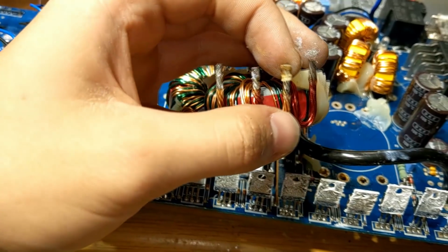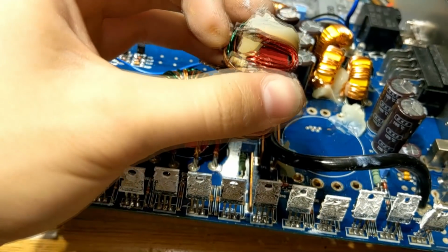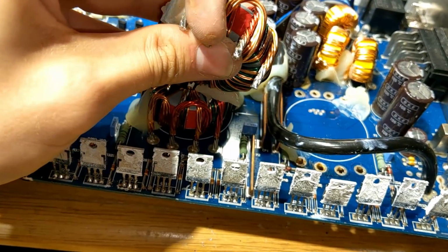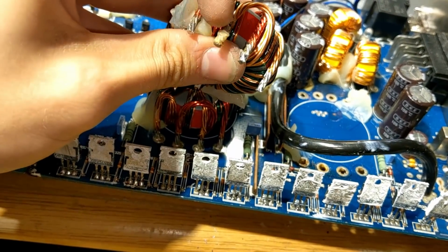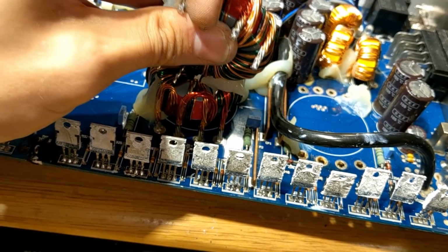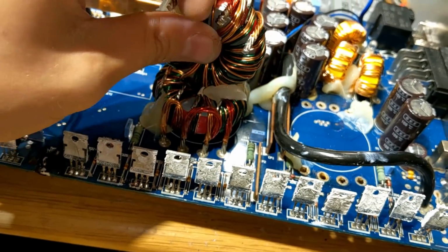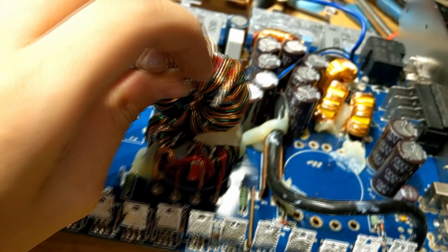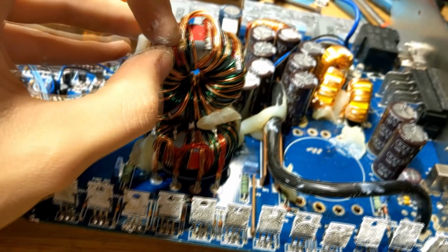So this protective silicon tip hasn't actually been removed from the transformer leg. Therefore, it was not making a decent solder contact into the PCB because obviously it's coated in the silicon protective layer. So just need to take that off, and then this should work like new, or better than new in fact in this case.